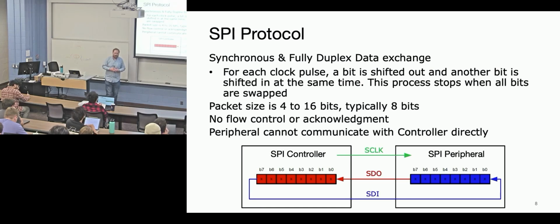Say you have a sensor, a common one would be an accelerometer, and your device is in free fall. The first iPods had discs in them, so when they noticed they were in free fall, they would take the head off the disc, so when it landed, they wouldn't damage the disc. That's a common idea. The problem here is your peripheral has to somehow tell the controller, move the arm out of the way because you're in free fall and you're going to hit the ground. So what's one methodology for getting around that?